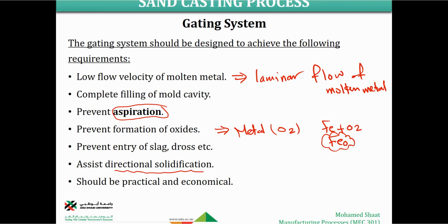And this directional solidification issue is a big deal, as I mentioned, in case we have huge castings, because what we would like to achieve during the solidification process of the casting is that all the metal should be solidified at once, at the same time.